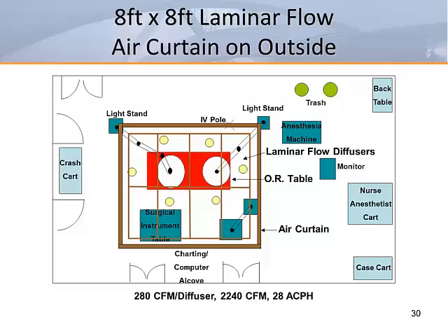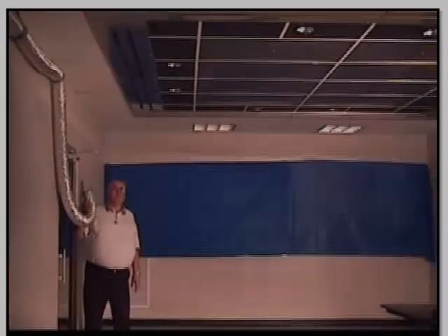For extended length surgeries, there is an increased risk in transmitting infection to the patient with these minimum standards. The most difficult staph infection to cure is when it attaches to a bone. So, add surgical suites doing bone surgeries to the critical list. For these critical surgery suite rooms, we recommend the use of an air curtain for added patient safety.